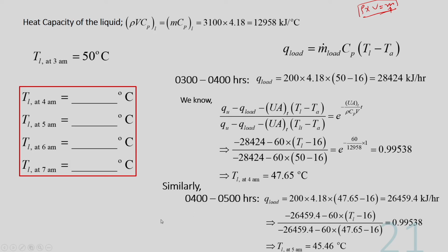Okay. So we need to find out at what time our heater has to be turned on. So first we need to calculate in the next step what will be the TL at 6, then we have to rectify it, the correct values of TL at 6. So after corrections what we get is 43.79. So what I mean to say, when we do the calculation for TL at 6, we have to confirm what is the temperature. Once it is found that it is less than the temperature 45 degree C at which heater has to be turned on, then it is confirmed that we need to turn on the heater after 5 hours.